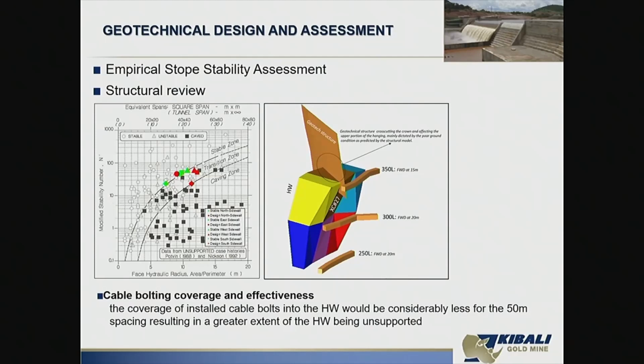So cable bolting coverage, as we increase it, especially to 30 to 50 meters, that becomes an issue. Usually you don't have a very good coverage. The cable bolts become ineffective because you are not really pinning into the wall properly, because it's much wider. It requires a much longer length of cable that you have to install.